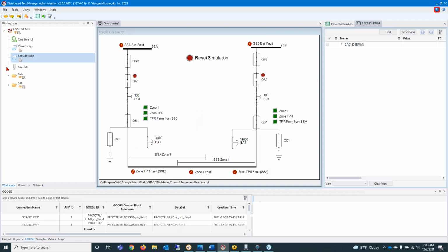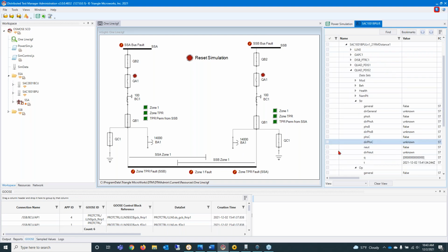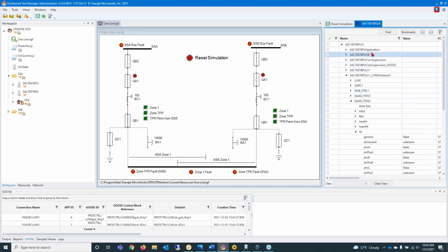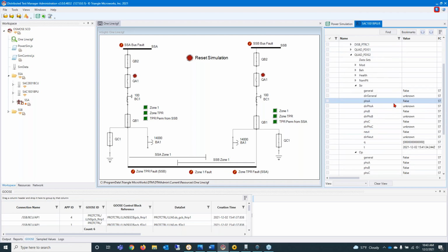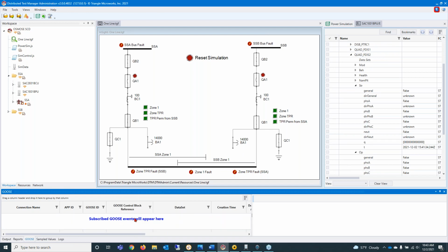The first thing we've added is obviously the IEDs to the substation. And because we have these IEDs, which are doing reporting and GOOSE and everything that you'd expect from a 61850 server, I can even open up this model here and see all of the logical devices, the logical nodes, data objects, data attributes, everything like that. We also at the bottom here have a GOOSE tracker. So when any GOOSE message is sent, we'll be able to see that happening in real time as well.